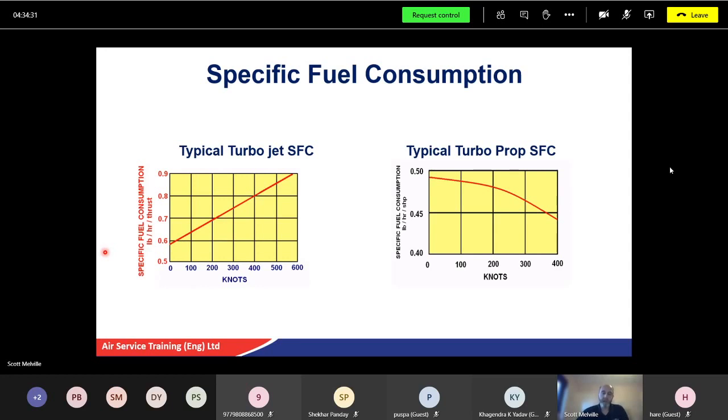It says in the notes there, high thermal efficiency requires high pressures, which in practice also means high turbine entry temperatures. In a turboprop engine, the high temperature would result in high jet velocity and consequently lower the propulsive efficiency. So it's about getting a balance. The core engine of a turboprop has to turn the propeller and only produce a small amount of thrust, because with the turboprop, it's the propeller that provides efficiency.